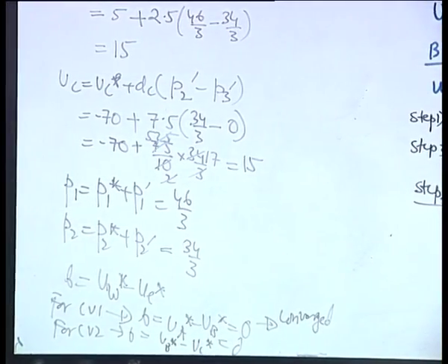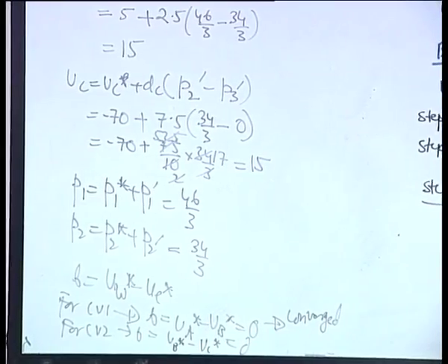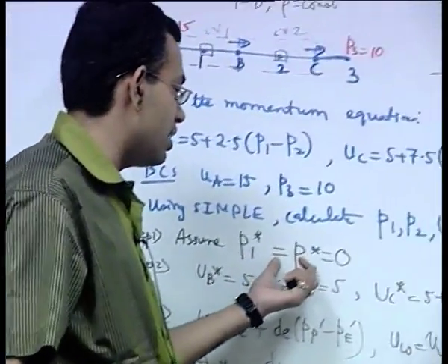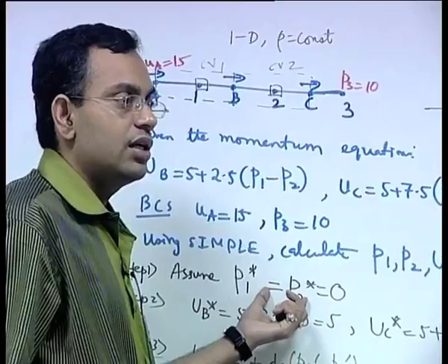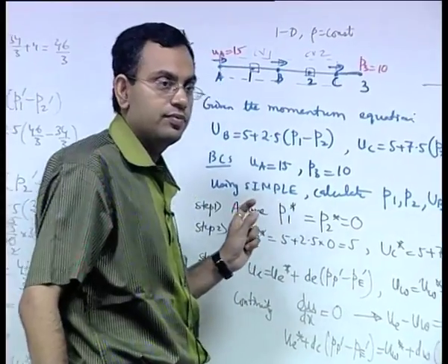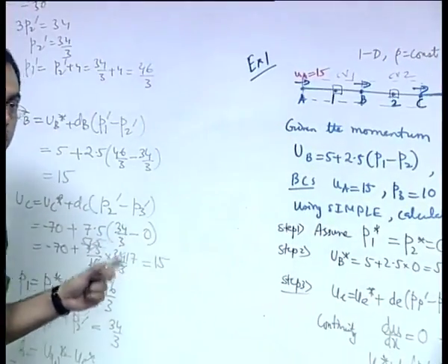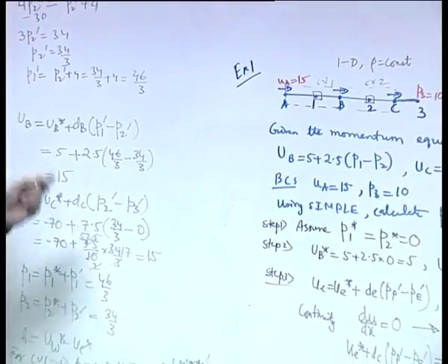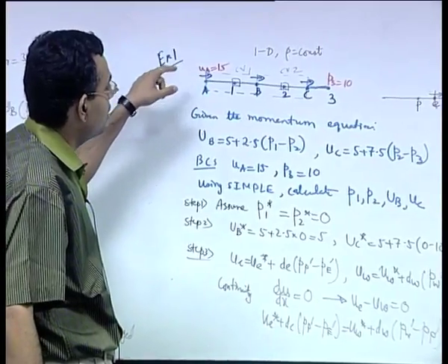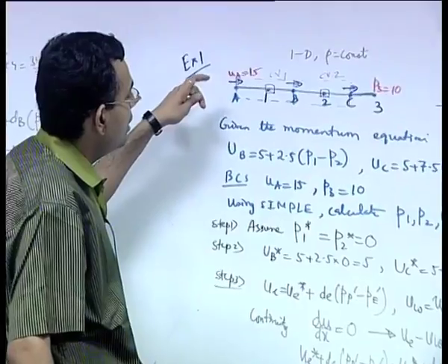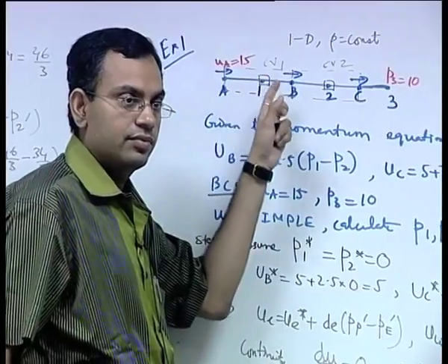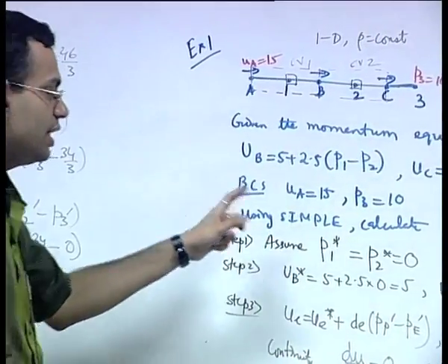So, it is a very interesting thing to note that irrespective of your initial guess in the pressure value, the SIMPLE algorithm in a one dimensional problem has converged just in one step of the calculations. And one of the important insights towards that is that the continuity satisfying velocity field in that case ensures the same velocity at all points, which is readily arrived at.